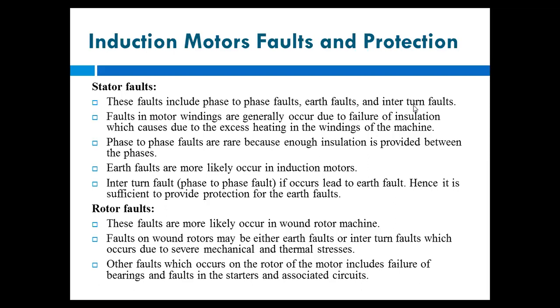So that's why the losses are more in the slip ring induction motor. Okay, and you may have studied in machines also that the slip ring induction motor has more losses. Okay, but there is one more advantage also, that we can add external resistance. So that type of motor is also sometimes preferred in some applications.